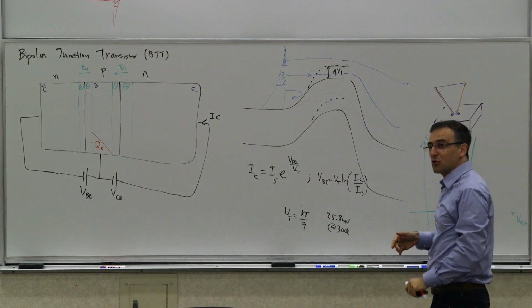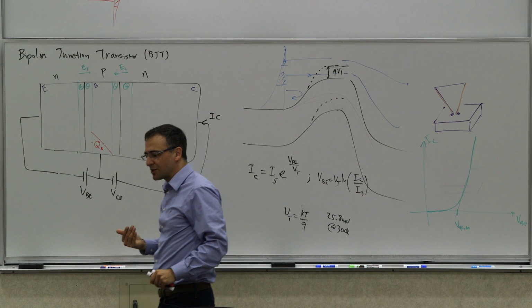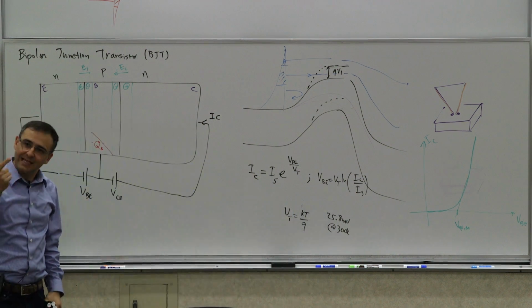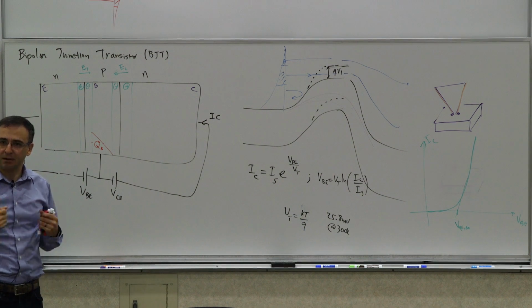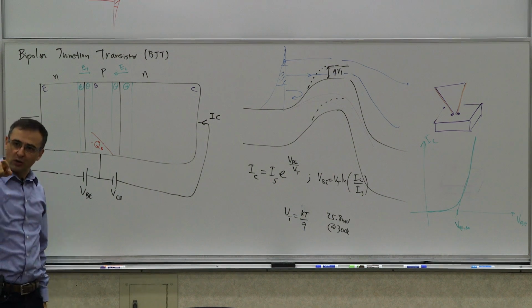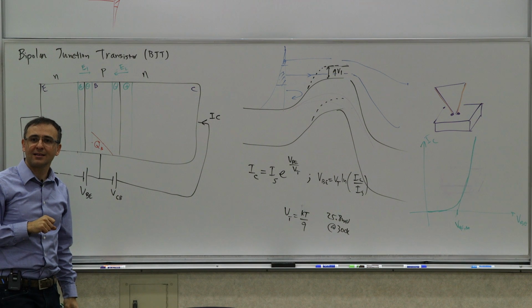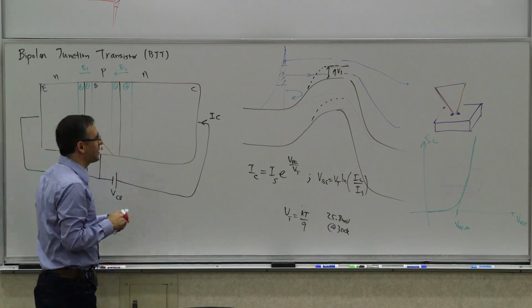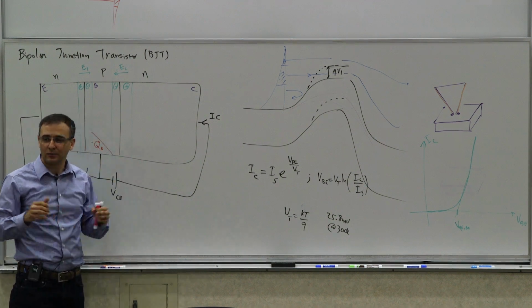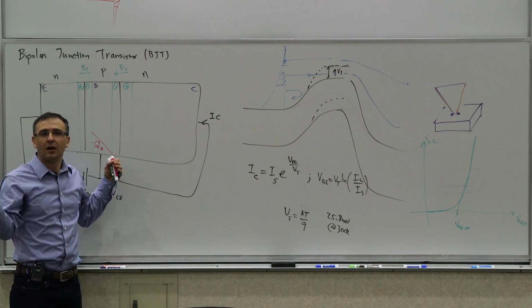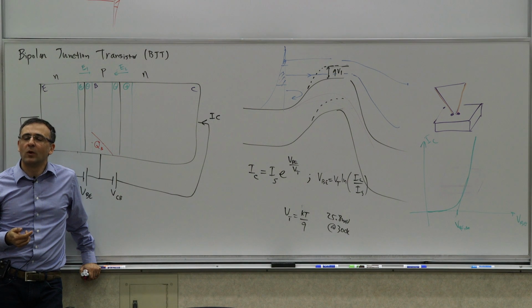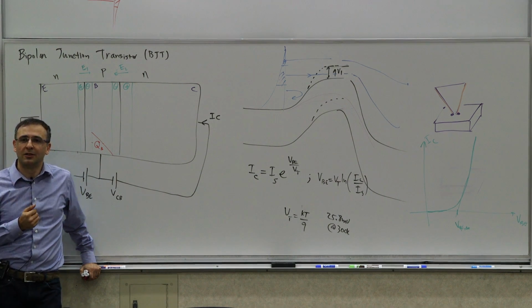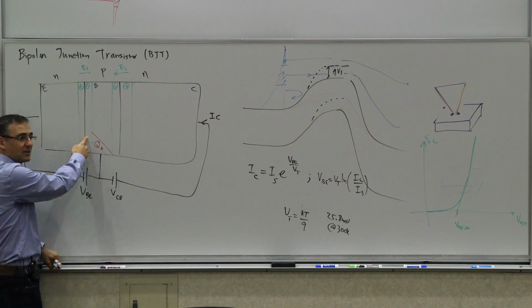So that brings us to an interesting related question, which is, let's say I'm interested in making this base thinner because I'm going to make my transistor better. And I'm trying to avoid the problem that you correctly identified, which is that the depletion regions will hit into each other, right? It's called punch through. That has a specific name. But what do we do? What do you think we can do? Increase the positive doping concentration? Yes, increase the doping concentration, right?